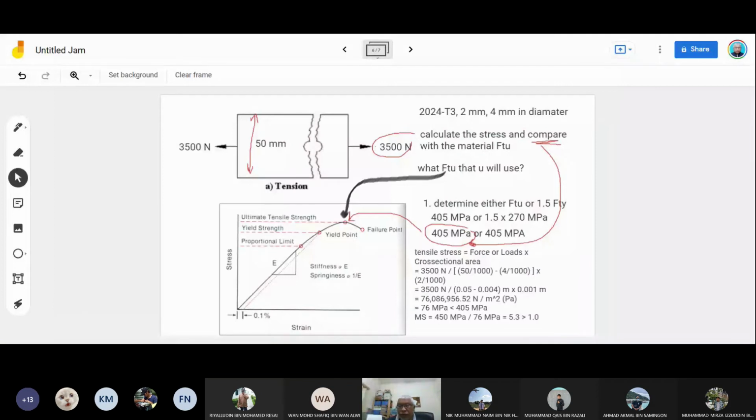And this report will be read by the authority, will be read by OEM, and that's how they will approve your repair. The repair approval is not just looking at the drawing, the most important thing, they will look at your justification of the stresses, your stress analysis on the report.